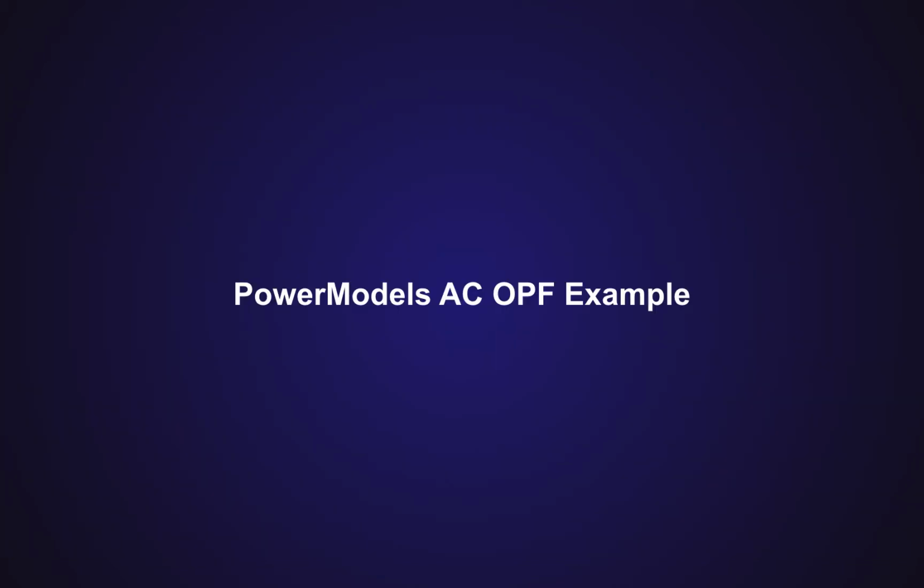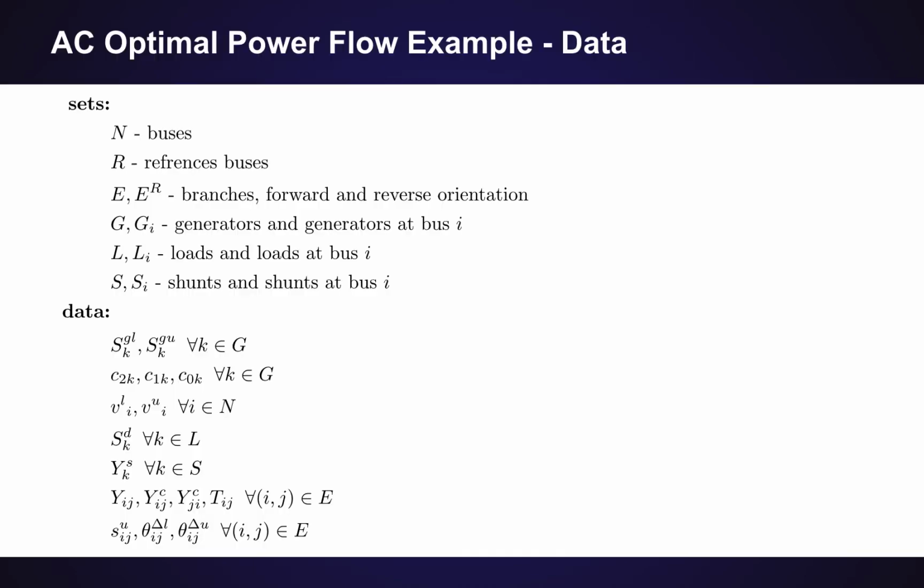So given those transformations, let me go over a basic ACOPF type of formulation that you'd have in PowerModels, so you can see that after we've mapped these particular formats into the PowerModels data structure, we can easily support this wide variety of test cases. This is the data that is coming through in an abstract sense inside of PowerModels.